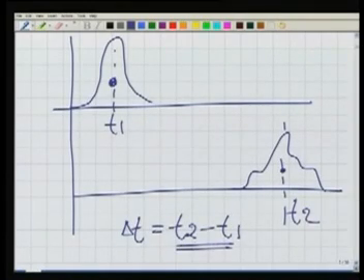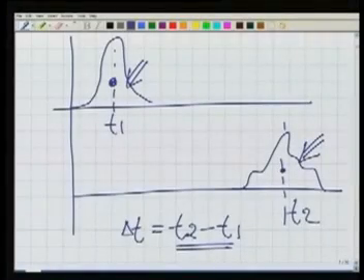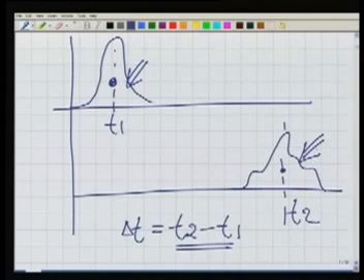Now, how are these times measured? Actually, there is electronic circuitry inside the instrument, and it makes use of that circuitry. It basically captures the return waveform. The moment one pulse is fired, it captures when this pulse was fired, then it waits for the return pulse. So, when the return pulse comes back to the instrument, it captures the return waveform. The return waveform could be like this. The waveform which was fired is a Gaussian waveform, but the return waveform may have any shape. It will depend upon what kind of reflector is there, what kind of surface is there.